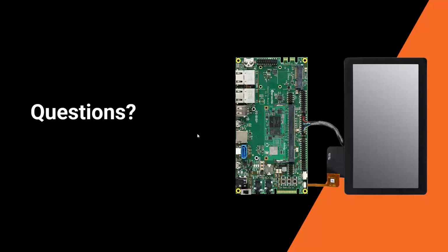But SDL is a graphical library, if you are aware of it. Basically, SDL comes only for the Wayland backend. And we are back to the initial requirement of the community. Since the target here is for low-end and low resources, we are focusing on the 6UL that does not provide the GPU. But still, you can build it using the Wayland backend and through SDL introduce the 3D support.